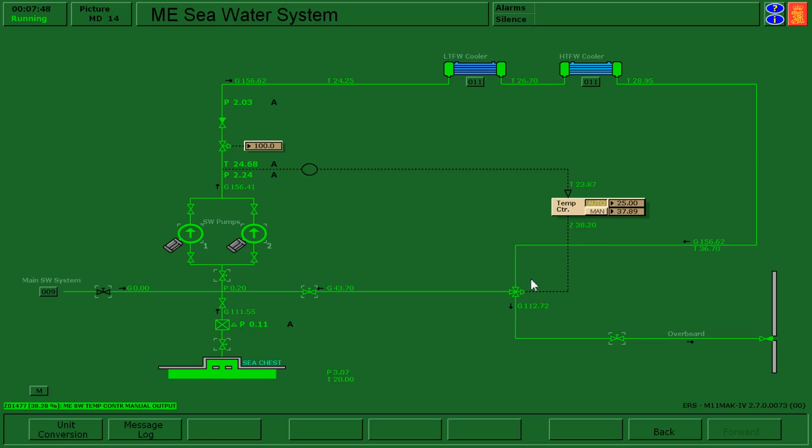And that's going to change depending on how much hot water needs to blend in order to set my desired temperature. And so I can adjust my auto. Say if I set it back to 22, then what it'll do is trigger a change to the valve position.